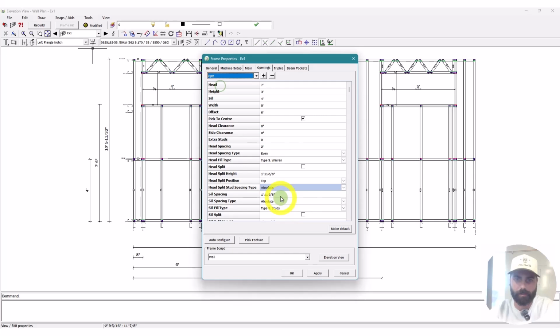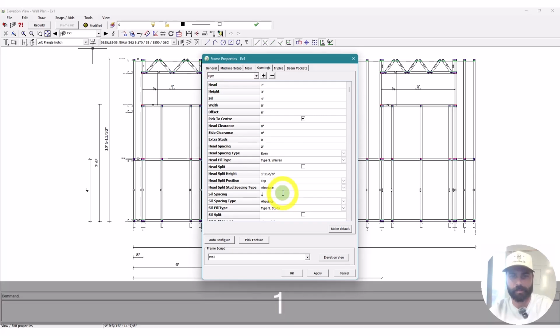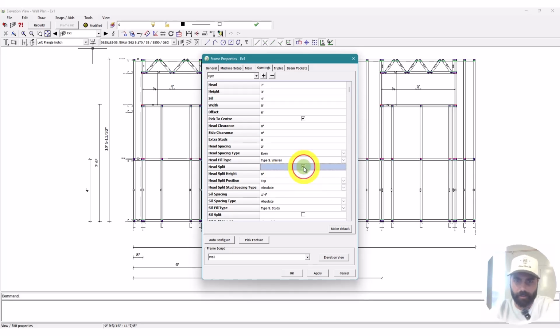And then we're going to switch this to 16 inches. Now the other thing that I noticed is this wall sits on the inside of the other wall. So I'm going to jump back and go to the stud reference. I'm going to edit this and it's going to be a -3 5/8. That's because the other wall is sitting inside.